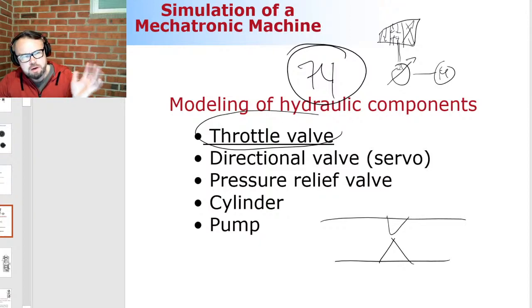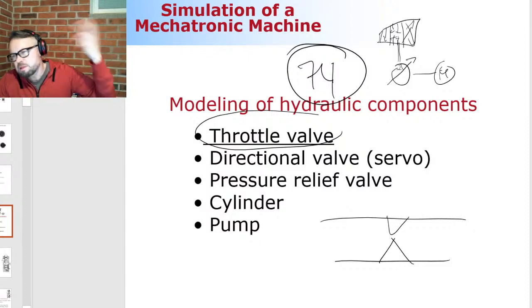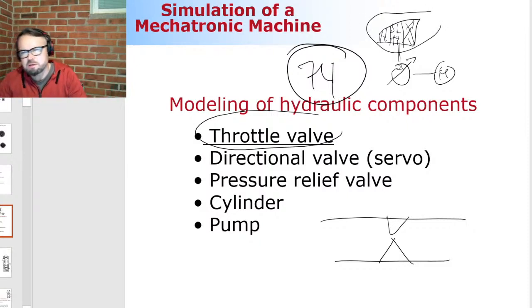And that's a little bit of a problem in hydraulics because you are first producing too much energy for your system, and then you're taking energy off using these control components like direction valves and others. But that makes no sense. And there have been some thoughts on how to get rid of this kind of problematic scheme. There is something called digital hydraulics that helps a little bit in this regard.